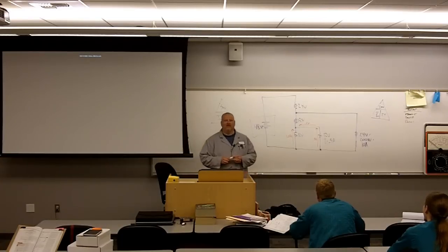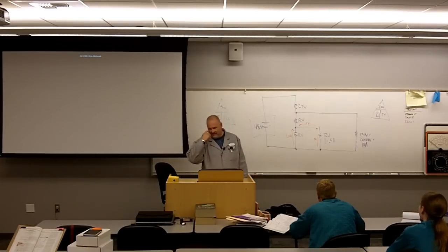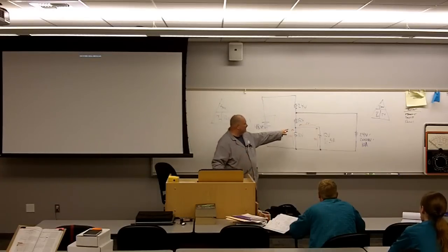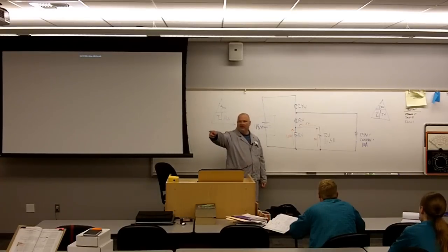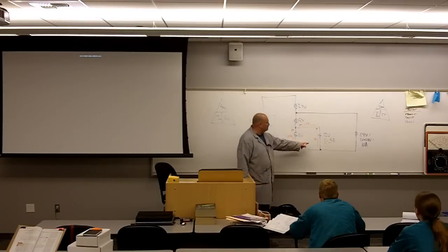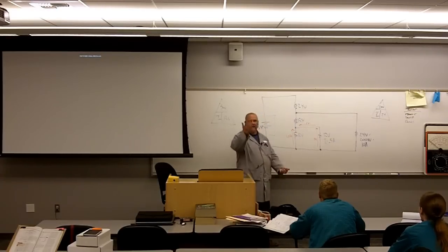Okay, but again, what's going to bring tears to my eyes is if you quote me laws. Are there any laws that govern what's happening here in this node? Absolutely. Kirchhoff's law. I got 1.05 coming up here. I got 0.5 here. We've got a traffic cop standing in the middle of that intersection. How much current's driving away from him?